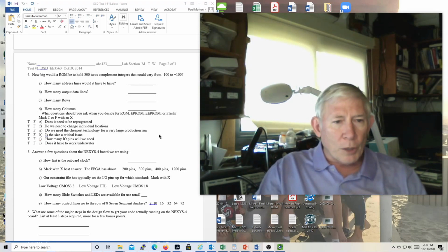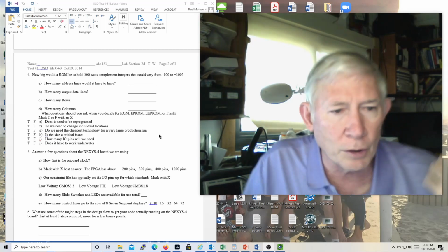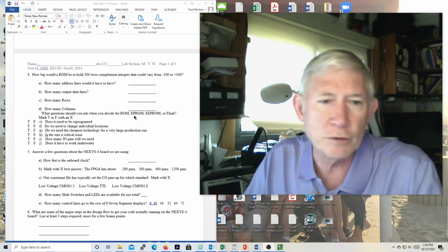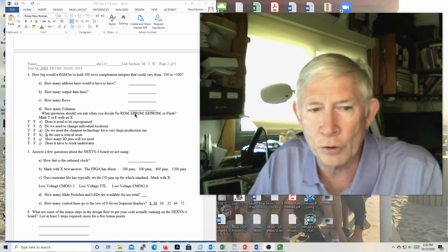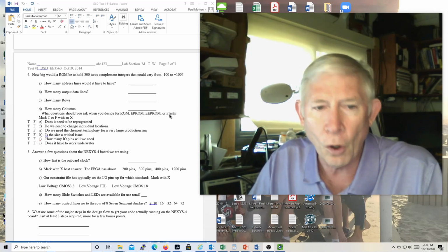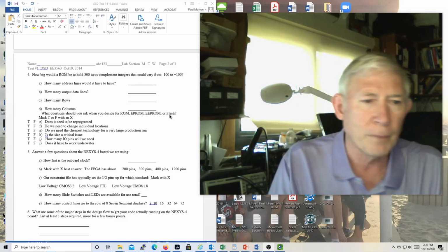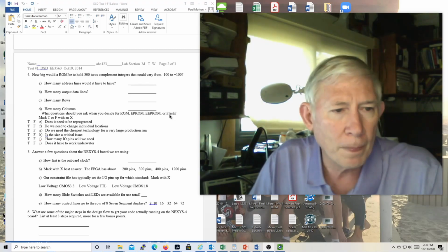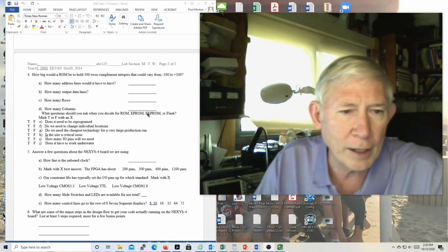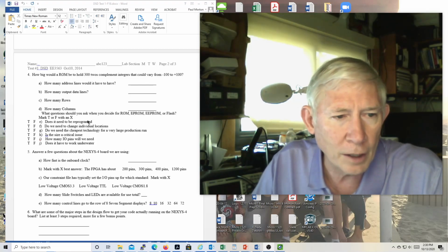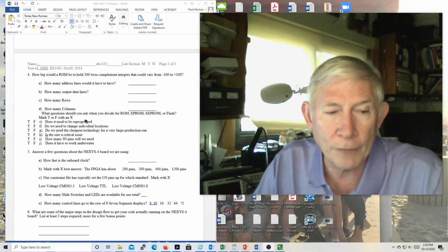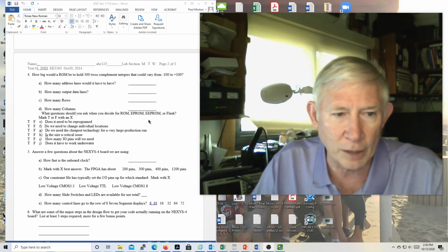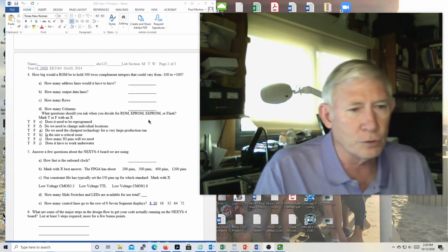Okay, what questions should you ask when you decide for either a read-only memory, a standard factory programmable, an erasable programmable read-only memory that would be, say, ultraviolet erasable, electrically erasable, electrically programmable read-only memory, or a flash, which is also an EEPROM? Does it need to be reprogrammed? So yeah, you would want that. Well, you definitely want to know that before you decide what technology you're going for. So yes, that's true. You need to ask that question.